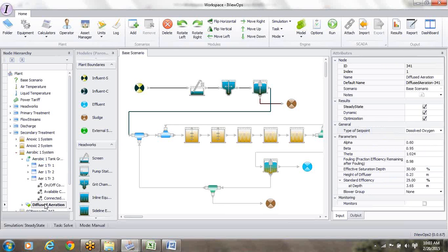Okay, next part which we have not covered in the anoxic is, what is the alpha and beta, etc. Let's say the first aerobic zone has an alpha of 0.55. This comes through calibration with the plant, etc. Let's say we have membrane fine bubble diffusers, and their efficiency is 24% at 12 feet or 3.65 meter depth. We will cover how to assign which blower or blower group is servicing which part of the plant in a more advanced video.